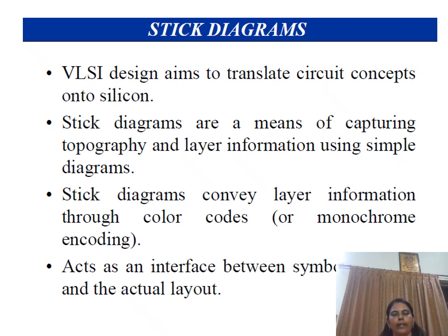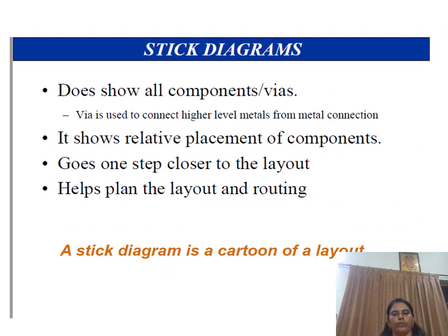Stick diagrams are rough sketches that will give all the layer information present in the circuit. A stick diagram is one step closer to the layout. A stick diagram is a cartoon of the layout. The stick diagram explains the rough estimation of the chip size.